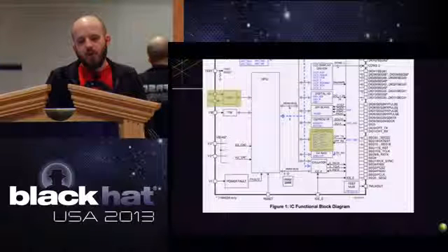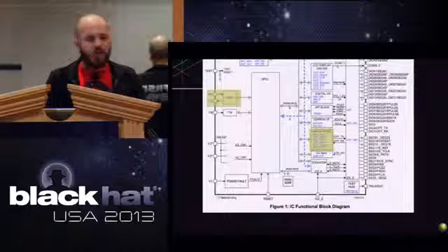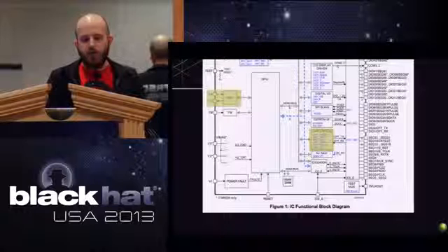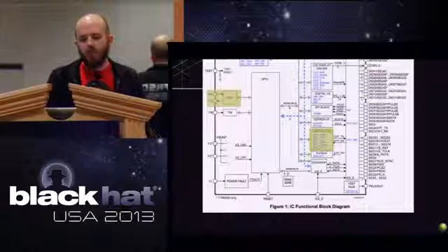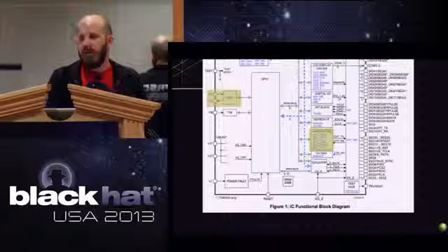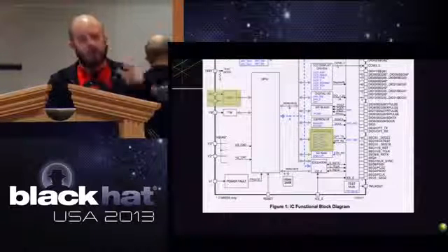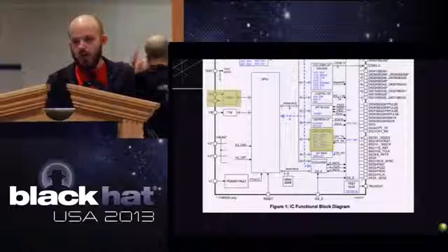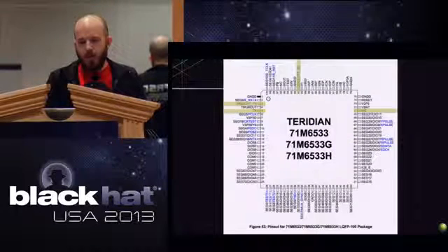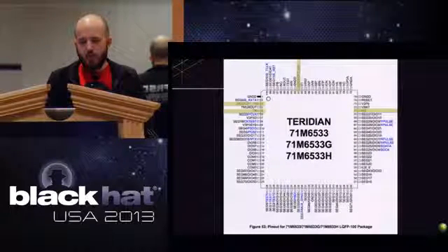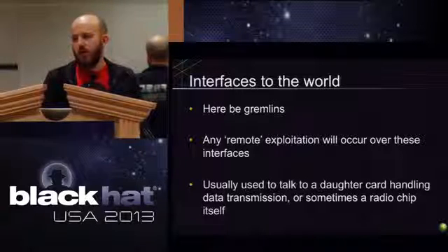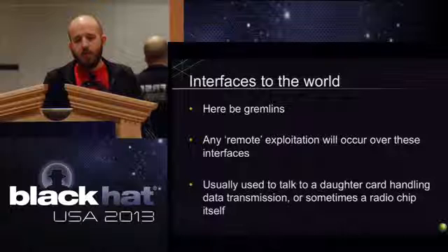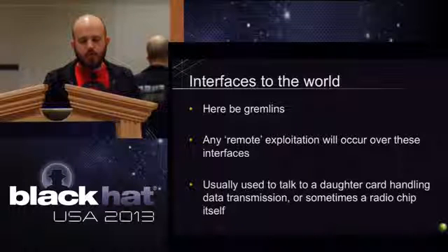All right, and then last case here, we'll talk about the interfaces into this guy. You've got a serial UART that's just standard like you would think, and then it also has hardware that's designed to speak to an optical interface on the outside. That's the looking into the eye of the meter, like Cutaways talked about last year, where they match on the pinouts. These interfaces are where all your problems are, because this is where you actually get to interface with code. So remote exploitation occurs over these types of interfaces.